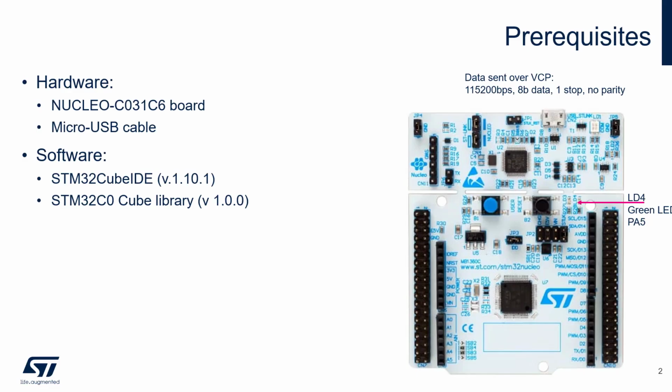Prerequisites. We'll use Nucleo C031C6 board and we'll connect this board to PC using micro USB cable. Concerning software, we'll need STM32CubeIDE in version 1.10.1 at least, and STM32C0 Cube library in version 1.0.0.